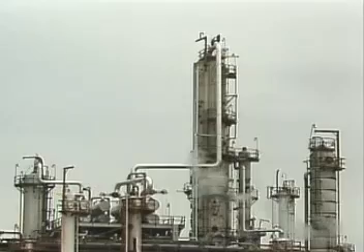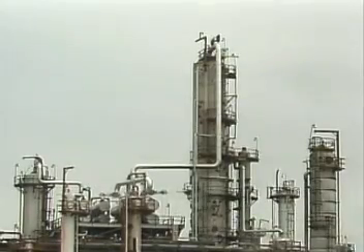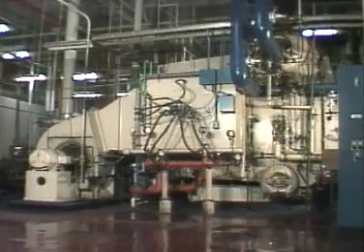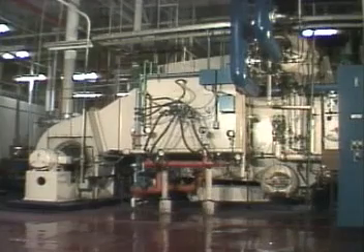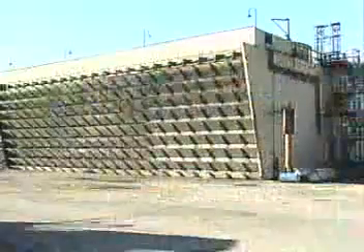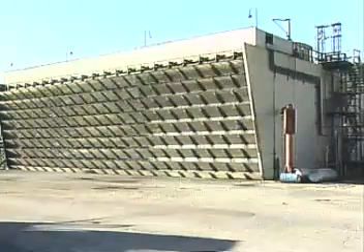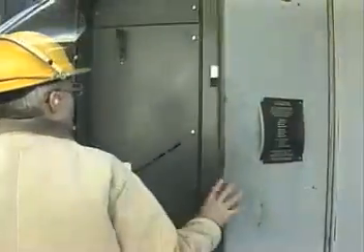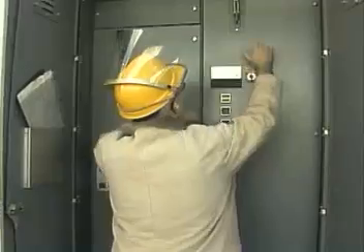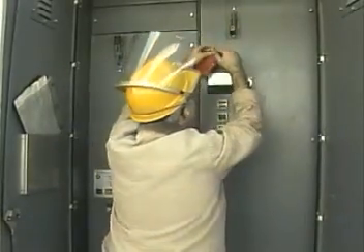Among the problems that can cause an emergency shutdown are a steam system failure, which could cause a loss of steam to the preheater, the reboiler, or the vacuum system; a failure in the cooling system, which could cause a loss of cooling water; and an electrical system malfunction, which could interrupt power to plant equipment. During an emergency shutdown, it's important to maintain clear communications with plant personnel and to follow company procedures. Following these rules can help ensure the safety of personnel and limit damage to plant equipment, the products being produced,